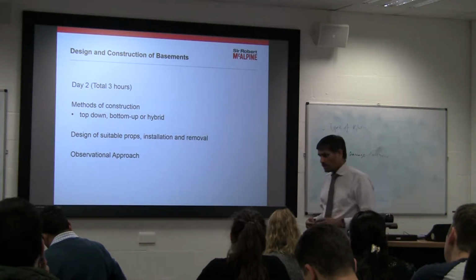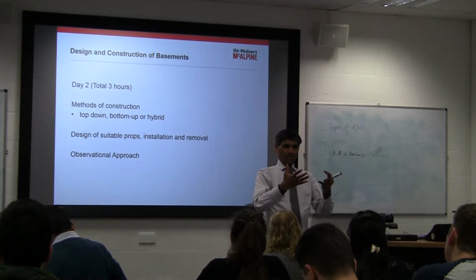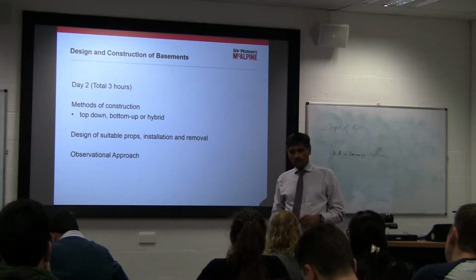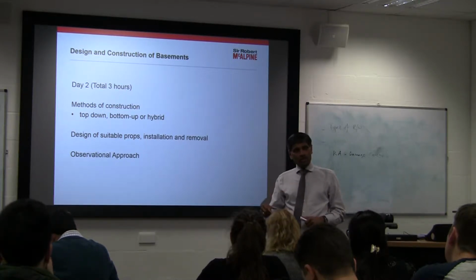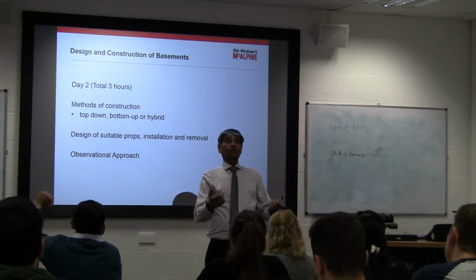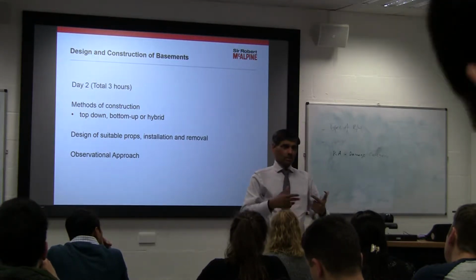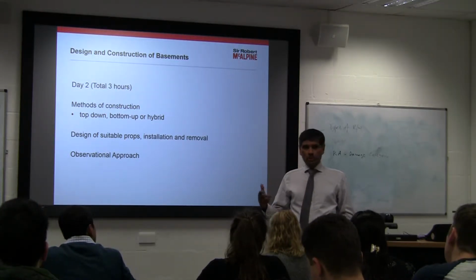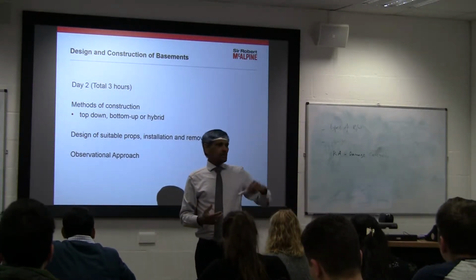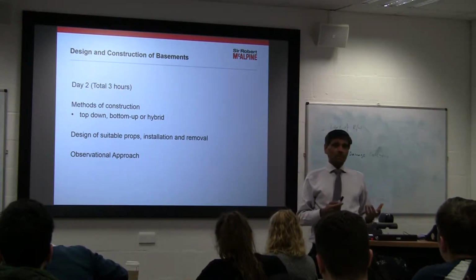You've got to remove them. So you've got to think as an engineer, how do we actually remove those props while the construction is going on? And then the observational approach is about a procedure where we put the monitors. Obviously, there's a lot of learning through this observational approach. It's like what you do in your laboratory. You take a sample, you test it, or you take concrete, you test it, you see the results, and then you improve on those. So the observational approach is an approach where you continuously monitor the systems, not just the ground, but all the surrounding properties.